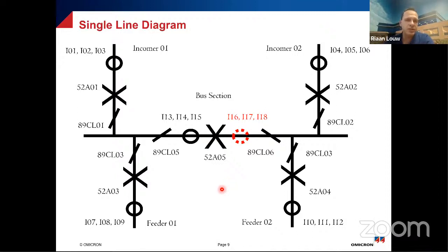So it's also important to mention that a lot of times when you consider the coupler security logic, there's 2 things you need to consider on the bus-zone side. In the one application, you can prioritize speed above selectivity. And if that's the case, you would not use the coupler security the way I've done today. This is typically the configuration that is used for HV schemes. I've gone for prioritizing the selectivity instead of the speed, which means if I have a fault over here, I'm not tripping out the zones as fast as I can, but I'm tripping out the section on an accelerated trip, and then I'm re-evaluating my system to take out the zone 2 instead of the zone 1.